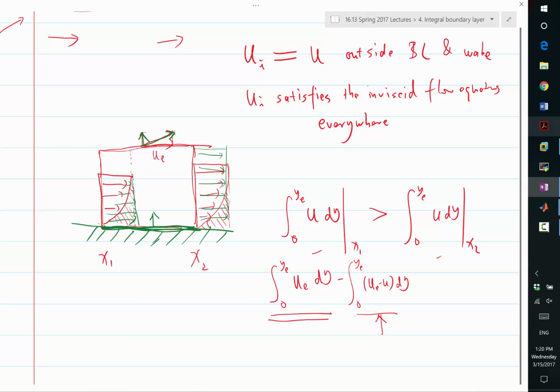Okay, you can think of the green velocity as some kind of extrapolation of the velocity outside the boundary layer. And because the velocity outside the boundary layer is smooth, almost constant relative to the thickness of the boundary layer, the velocity at the bottom of the wall is practically the same. X velocity is almost UE, and Y velocity is almost the same as the wall normal velocity of the streamline outside the boundary layer.